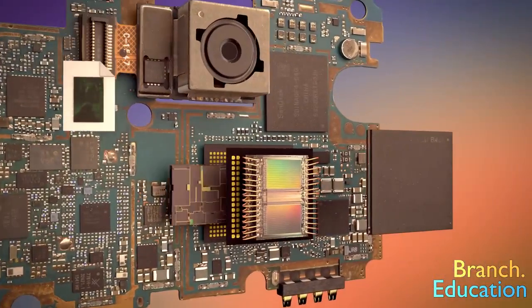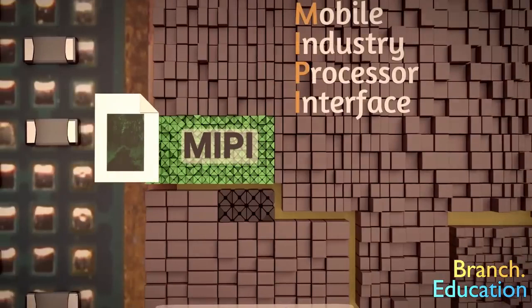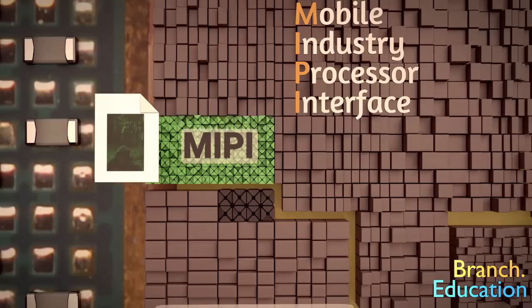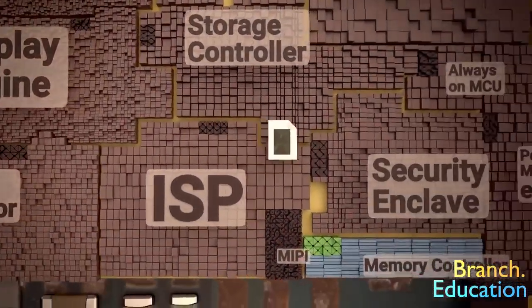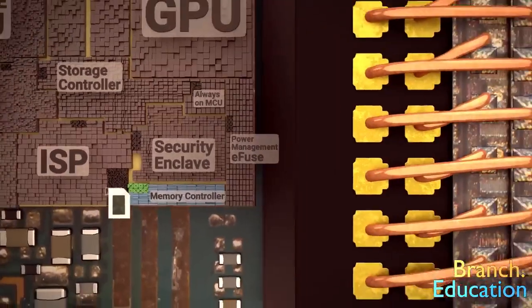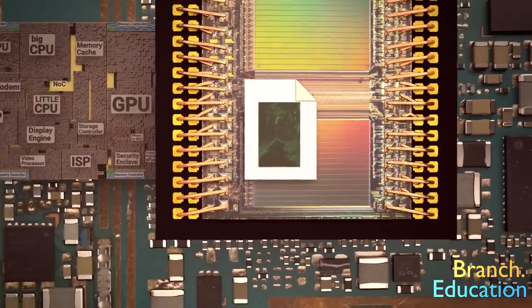To do this, the data travels from the camera and enters the SoC through a Mobile Industry Processor Interface, or MIPI, which can send or receive data at around 5 to 8 gigabits per second. This image data is then routed by the Network-on-Chip arbitrator through the SoC to the memory controller and into the DRAM, which, as mentioned before, is located on the die above the SoC. There are two quick things to note.